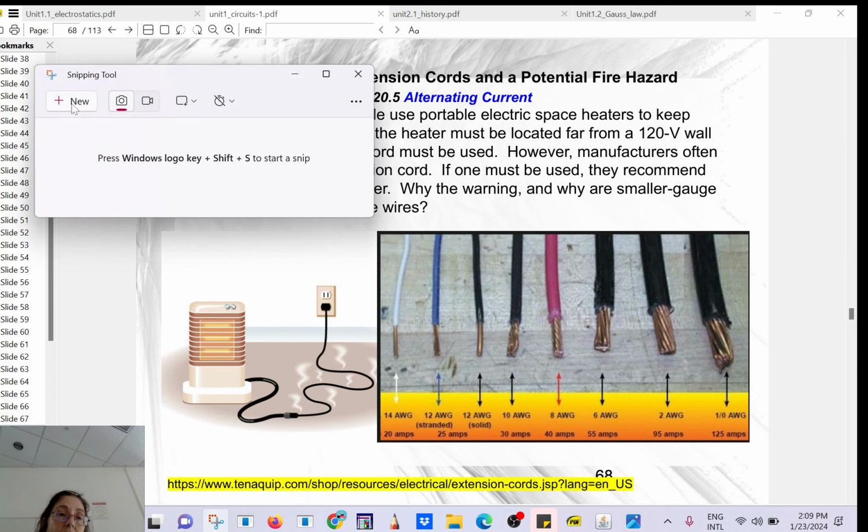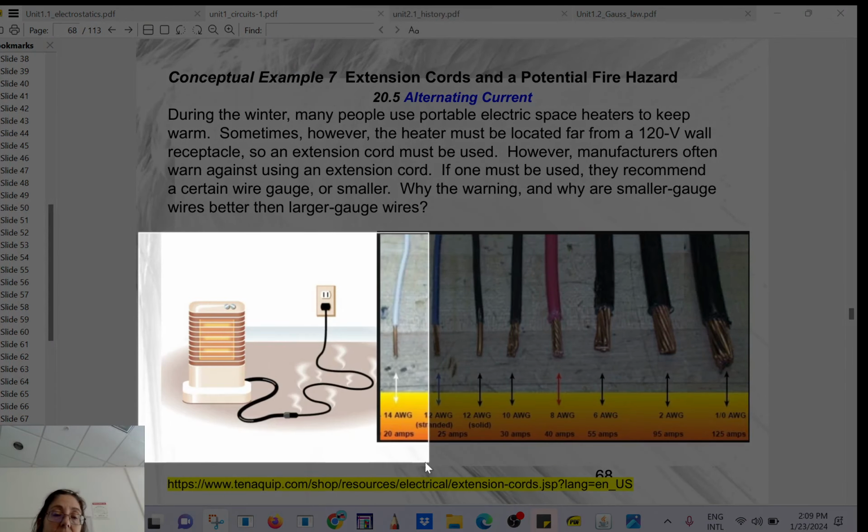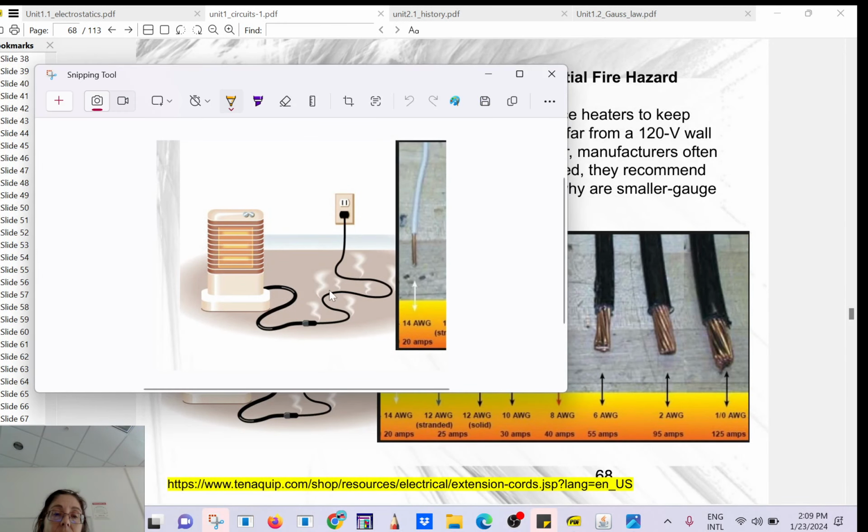So why do you need to use very thick wire in that case? Again, because of the amount of energy that will turn into heat here, you see, it's turned into heat here. That's because that wire has its own resistance. So the amount of energy that you are losing to heat, P, equals R times I squared. So it's not only proportional to R, but to I squared.